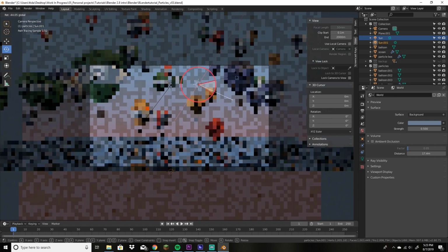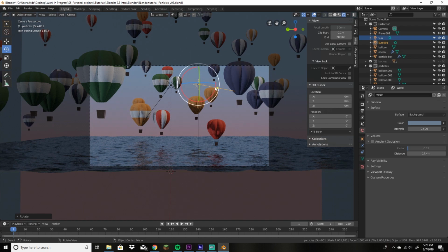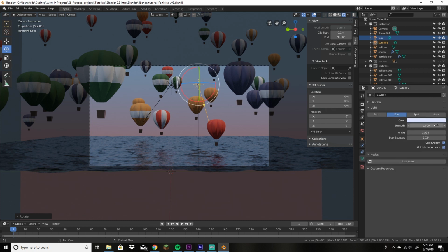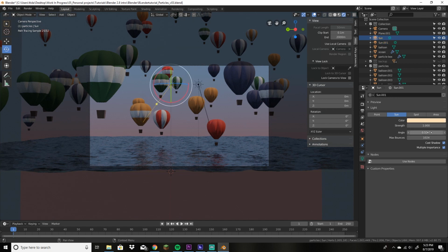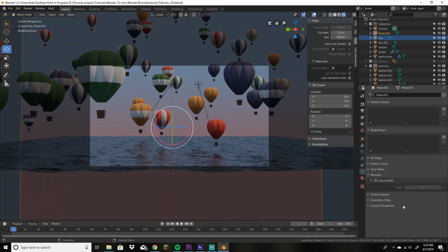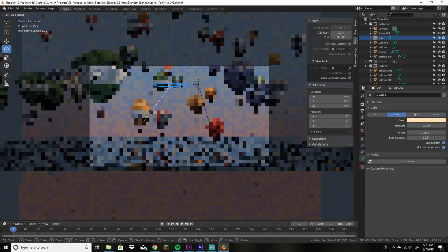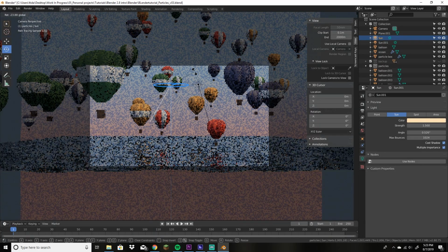I'm going to make this a little bit more extreme to help fill lighting right there. And the cool light should not be at a strength of 1. That should be at a strength of like 0.5. And the warm light should be at about a 1.5. That'll give you a good balance between the two. And now I think our lighting is getting very close to set.